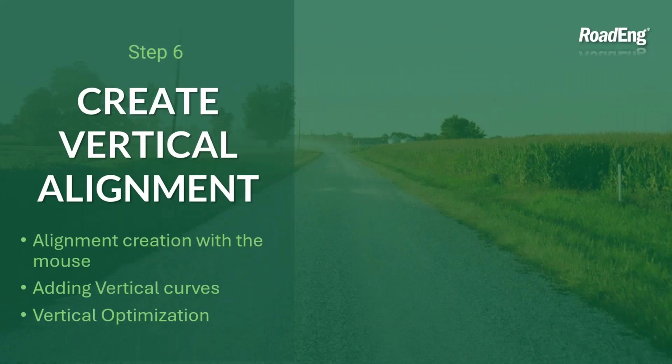Excellent. So one of the things that's worth noting, when we leveraged that polyline to alignment tool, we actually removed our vertical alignment. So if you saw it, Matt's alignment in the vertical profile window was actually just following the ground. So in this next step, we're going to create our vertical alignment. So creating a vertical alignment is really similar to creating a horizontal alignment. We've got a tool that can help us do it through optimization, but you also have the ability to create your alignment with your mouse. This is sort of that add edit IP tool, clicking in your different IPs, and then you can add curves to it. And I just wanted to quickly step through sort of what that process looks like.